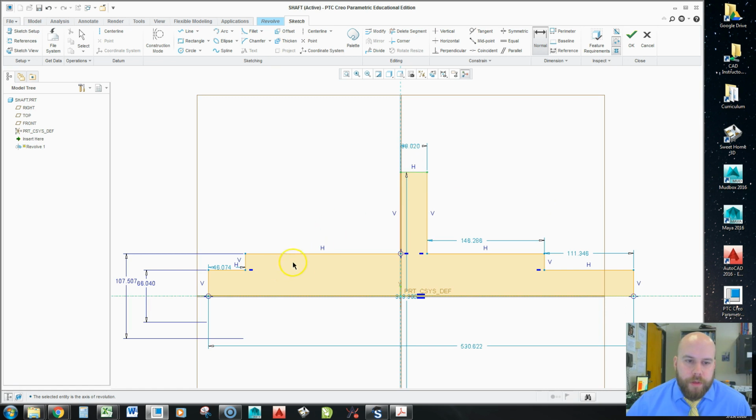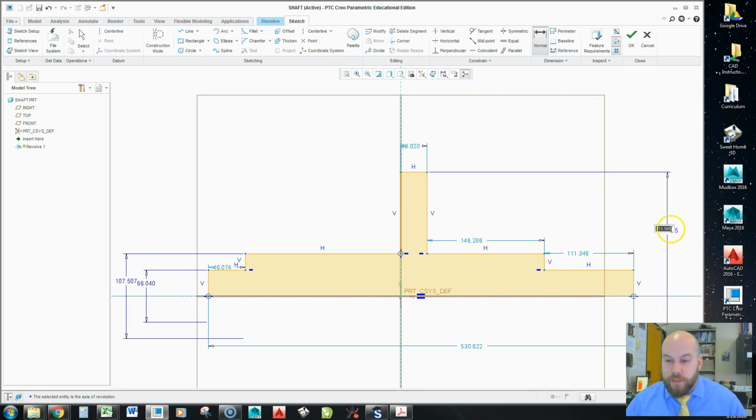And what we're doing when we do that, by the way, is saying I'm measuring from the outside of a circle to the center of the circle to the outside of the circle, which is really the definition of a diameter. Although typically it's from one outside point to the center, then to an opposite outside point. But this is how we do it in Creo for a revolve feature, since we don't have that other outside point down here. Okay, so now I've got that dimension in.